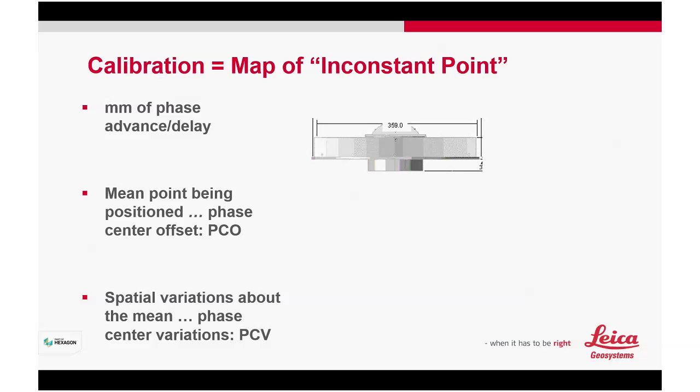Okay, and for some of them, if the manufacturer is not so good, sometimes we come to about a cm. Okay, the one term I'm using is the so-called phase center offset. This means the phase center and the point you contact, whatever the monument. Okay, maybe a carrier, maybe it's really the monument. How far away is the vertical offset from the phase center to your point. Okay, and then the second thing you talk about is the phase center